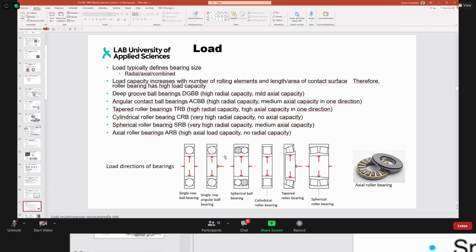So is the angle defined by the design of the outer and inner ring and their groove? Yes. So basically the height of this shoulder defines what the angle in the contact area is. I see, these grooves, the shoulders, are symmetrical, right? Exactly so.